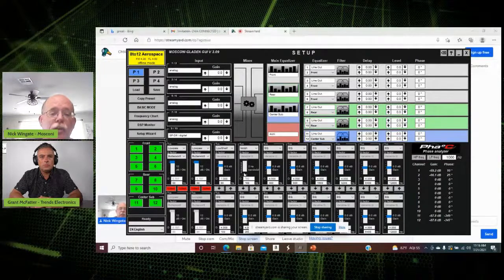And if it is, do this. Start raising the bandwidth. Just click on that slider and raise it until it literally goes away. And it will go away. It will become a null. It will just flat go away, instead of having to figure out what's resonating and trying to find it. No, just use a notch filter. And again, if you've got it in both doors, transfer it over. If not, the other door, we may have a problem.